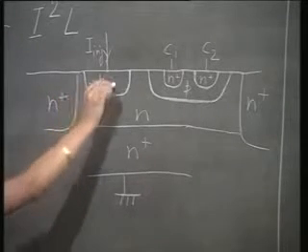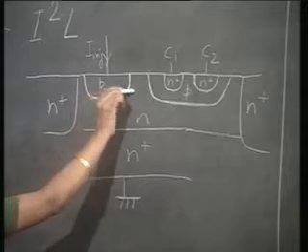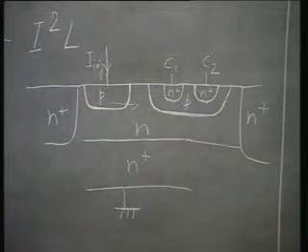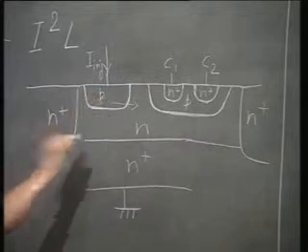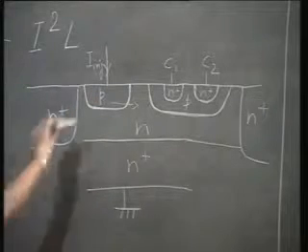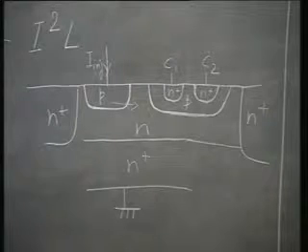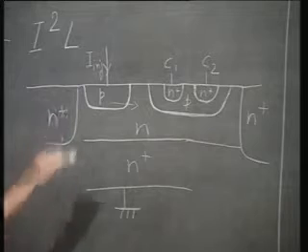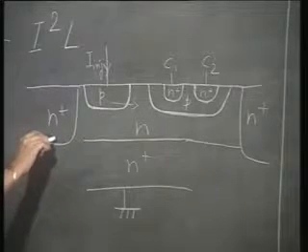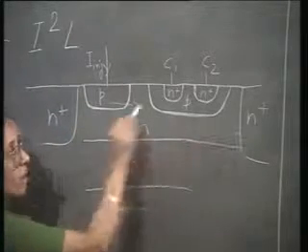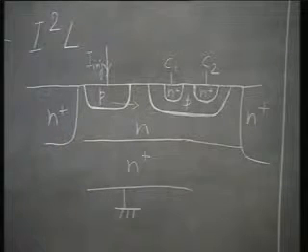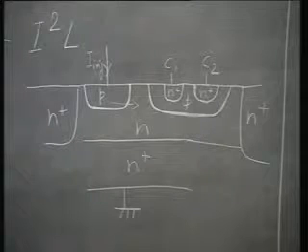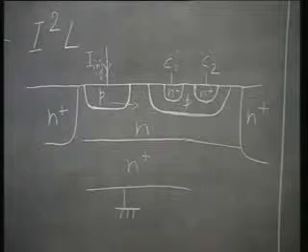You want the hole injection in this direction, P and P. However, as far as holes are concerned, it does not see any difference between this direction or this direction. However, if you add this N plus collar, then because the doping concentration in these regions is going to be far more than in this region, the hole injection will be predominantly in the active direction, in the direction you want it.